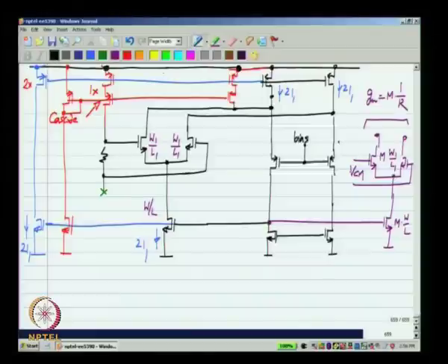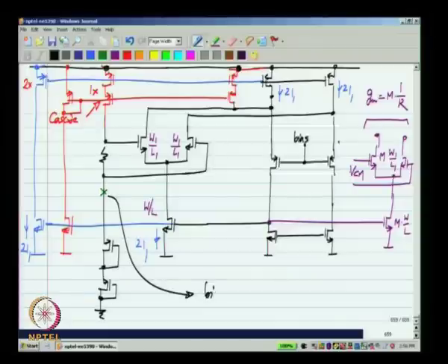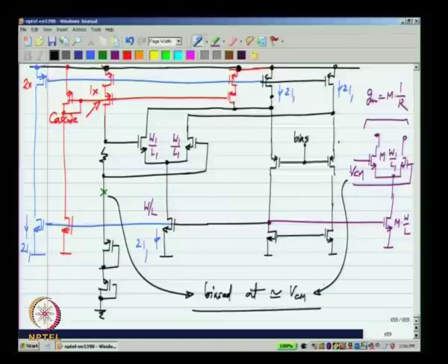So, what you do is you use whatever biasing arrangement that is possible, like for instance you can simply use a diode connected transistor, 1 or 2 of them. Okay. Basically the point is to bias this at approximately the VCM of the differential pair that you are using, so that the differential pair whose GM you are locking to 1 over R and the differential pair that you are using are operating at around the same condition.